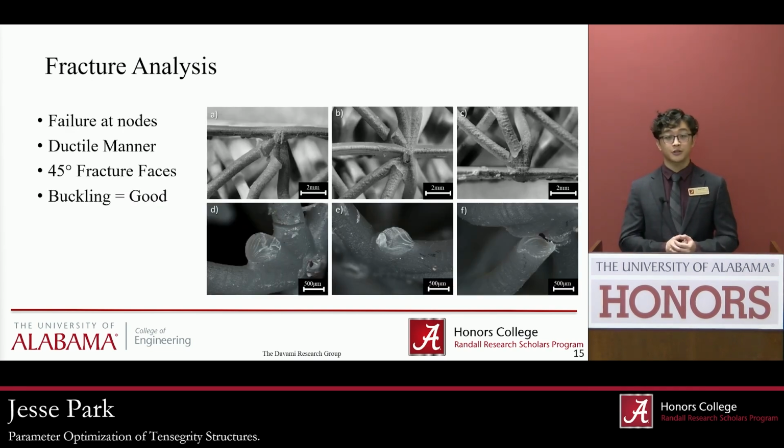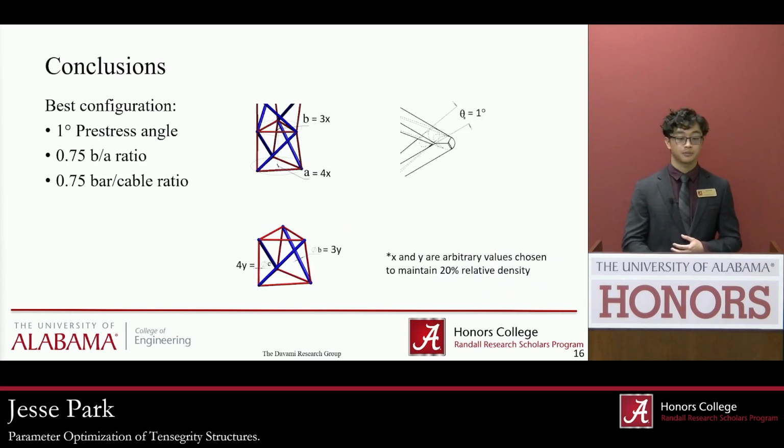We also conducted fracture analysis using optical microscopy. What we determined was that the majority of fracture happens at the nodes in a ductile manner with 45-degree fracture faces, signifying buckling, which has been shown in other literature to maximize the strength to weight ratio.